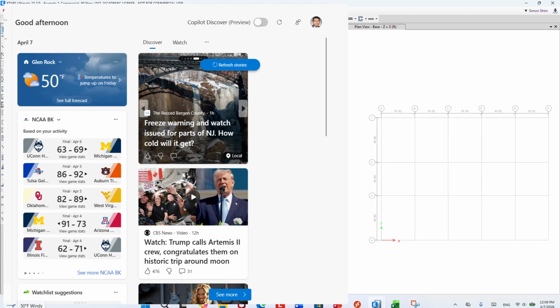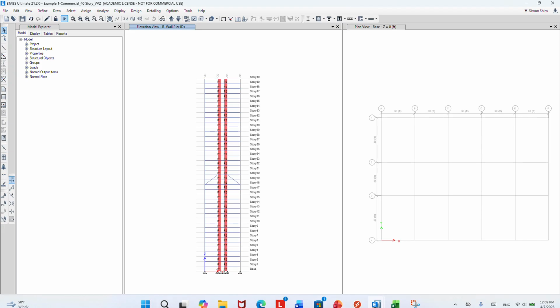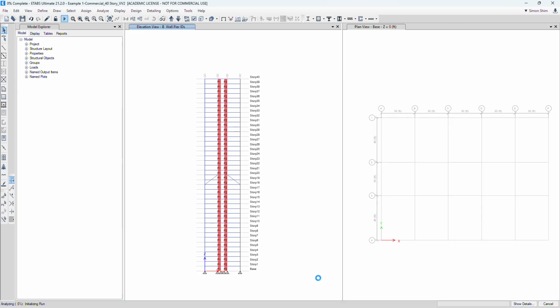What I'm going to show you is the same thing, the load path. Last week we talked about load path among each system. Since we are adopting outrigger with concrete core wall, coupled shear wall with outrigger, we need to understand the overall load path under the wind load.